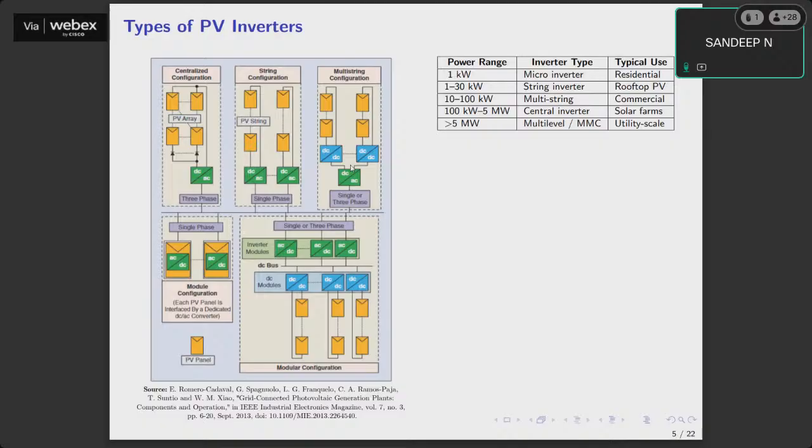So one of the challenges is that if the inverter fails, then this entire system has to be shut down, right? Even though we have PV generating power and DC-DC converters are working fine, we don't have the central link, the bridge between DC and AC. So that is one of the challenges. However, this would be less costly as compared to this. Anyway, cost is a different issue.